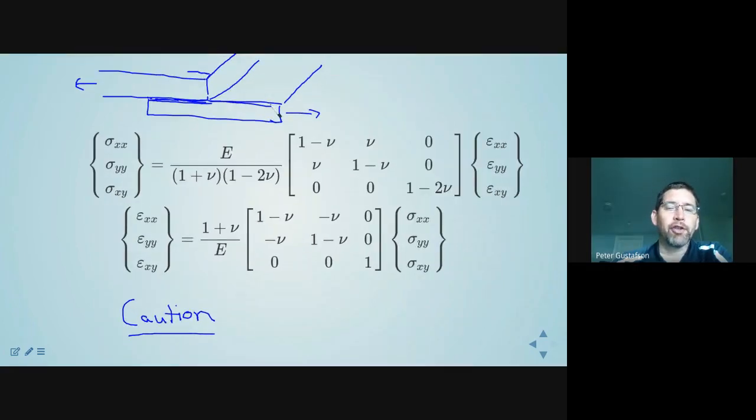So if it's very thick in the z direction, then plane strain would probably be a very good assumption, because the stiffness of the lap joint substrates themselves would dominate the strain in that z direction. But if this were really thin, then it wouldn't be a good assumption. So again, these are all circumstantial. And typically the plane strain assumption is going to apply when you're using something like an adhesive, and in one direction, it's very long compared to the other directions. So very stiff materials that are oriented very long into the depth. That would be a great time to use plane strain.